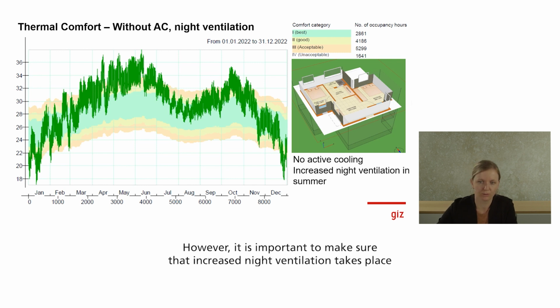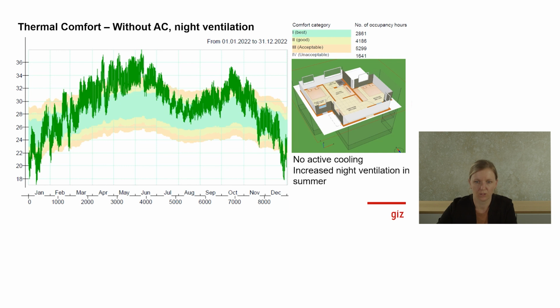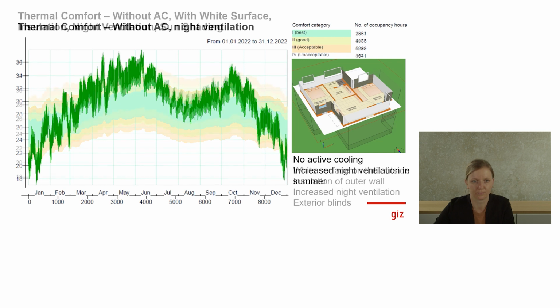However, it is important to make sure that the increased night ventilation takes place only in the warm months. Otherwise, the room would cool down too much in the cold season, which in turn would increase the number of unacceptable hours. Here we have calculated with increased night ventilation only from March to October.